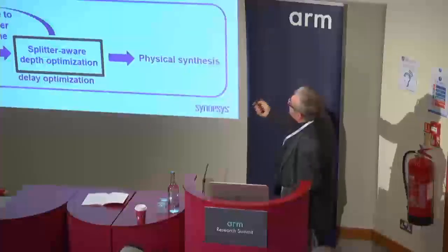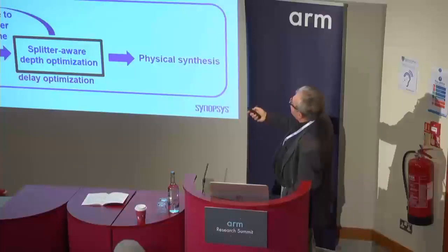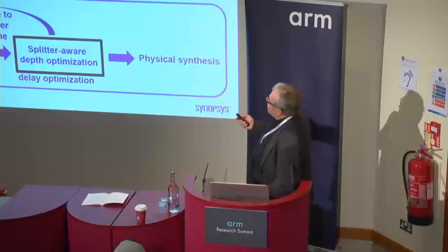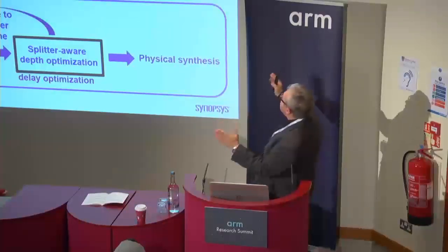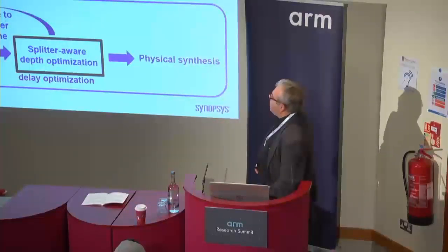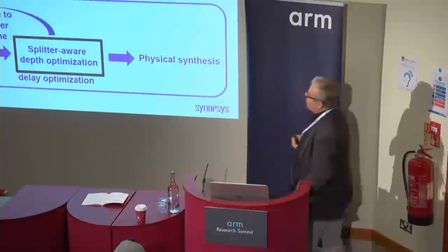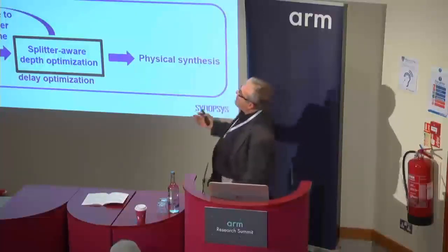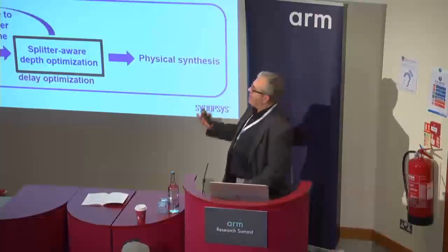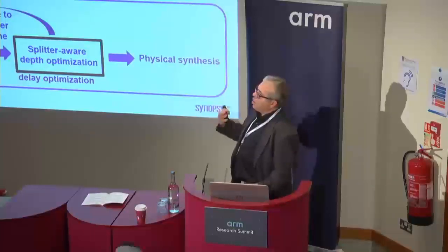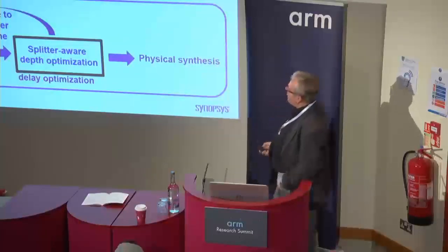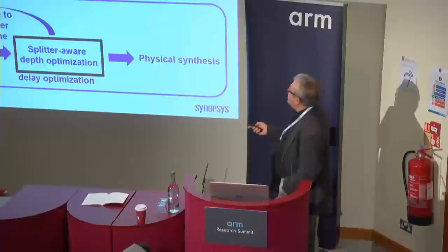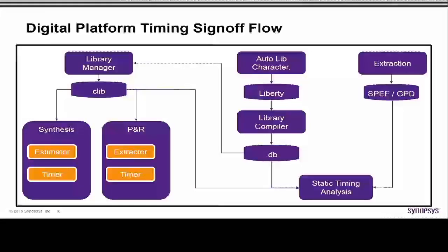Again, you have two sometimes conflicting objectives. On one hand, you want to minimize the number of Josephson junctions and therefore minimize the area. On the other hand, you want to minimize the depth of a pipeline because that really impacts the local frequency at which you operate. And really, we are already reaching the conclusion that for VLSI, you have to follow a GALS approach, which is globally asynchronous, locally synchronous. I will leave it at that for this slide.